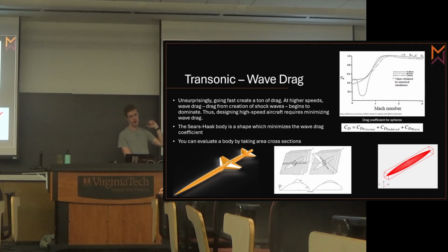Another big problem for us trying to go up to Mach 1 is that the coefficient of drag increases rapidly as you approach that speed. What's the name for it? Do you remember? I thought there was a name for it. It was something barrier. Yeah, drag barrier or something. Between I think Mach 0.85 and Mach 1, it's a threefold increase in drag, something on that order of magnitude. So it becomes much harder, and doing wave drag stuff like this helps you out.